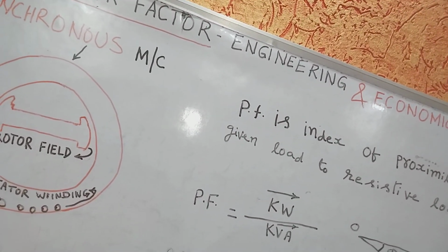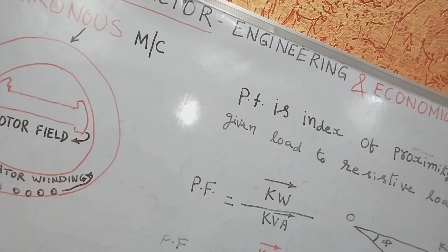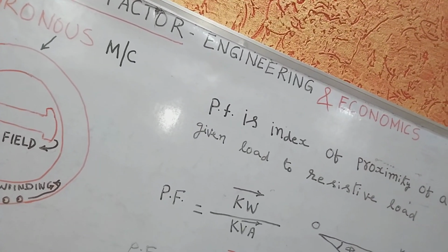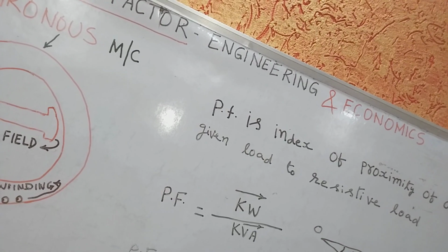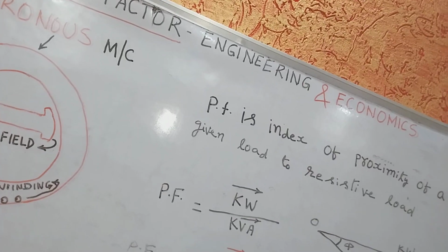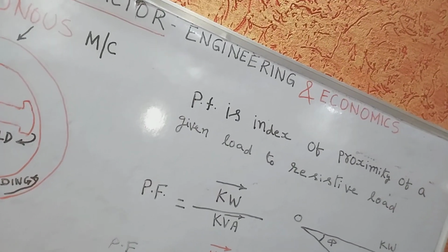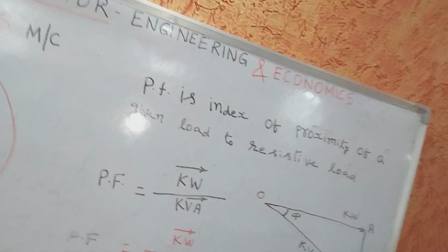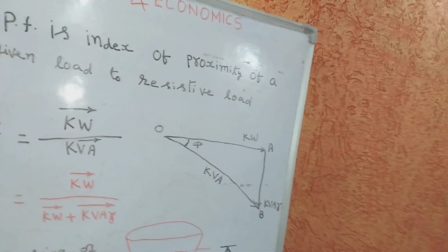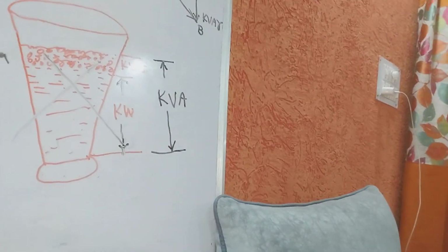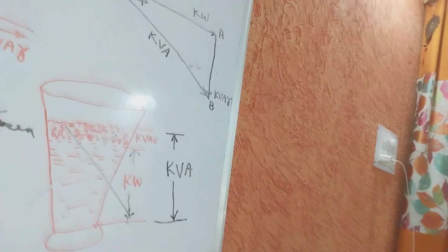If the field current is less, that is, the motor is underexcited, the deficit in MMF must be made up by the armature and the motor operates at lagging power factor. If the field current is greater, that is, the motor is overexcited, the excess MMF must be counterbalanced in the armature, and a leading component of current is present. The motor then operates at a leading power factor.